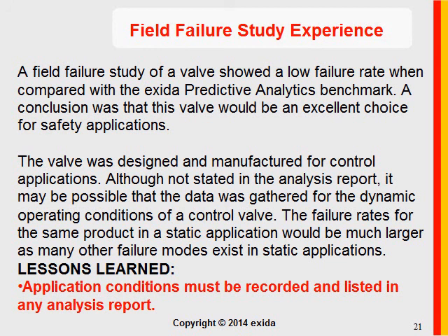So stiction problems, we're not looking at. Your typical stuck stem, those failures will not be detected or will not be recorded in a dynamic operation application. So in this case, failure rates that were recorded will simply not be applicable to static applications. So we need to look at where the data is coming from.